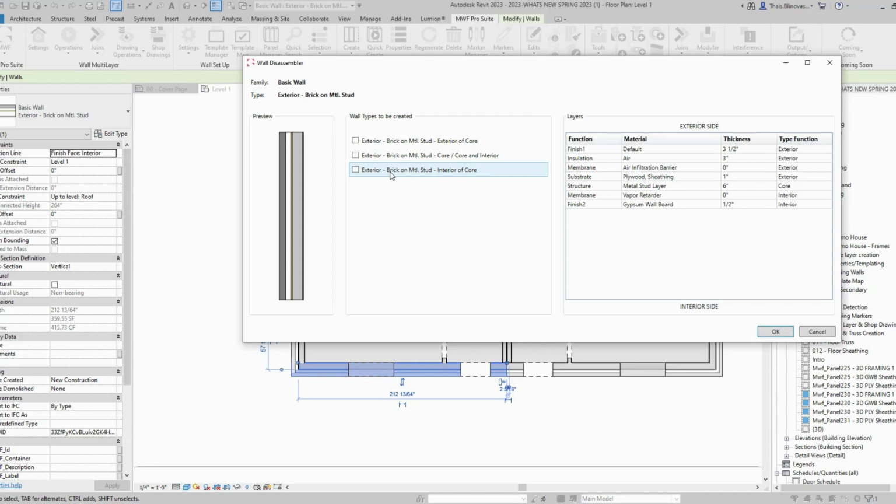So even though they are going to be separate panels, the sheeting will be able to refer to that structural layer. So you can split the sheeting boards, for example, where the studs are, and not have them splitting in random places.